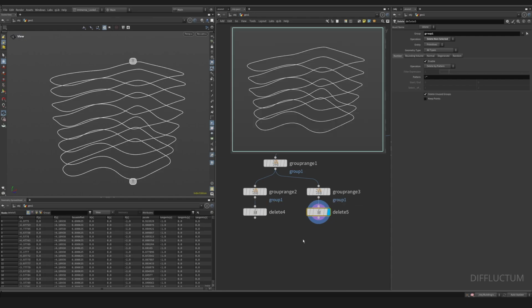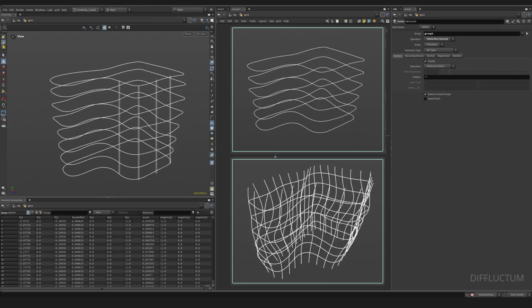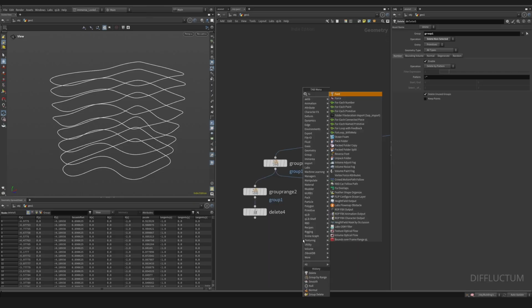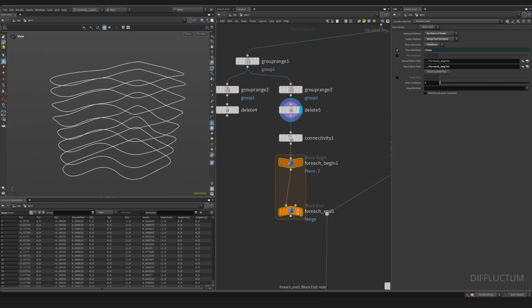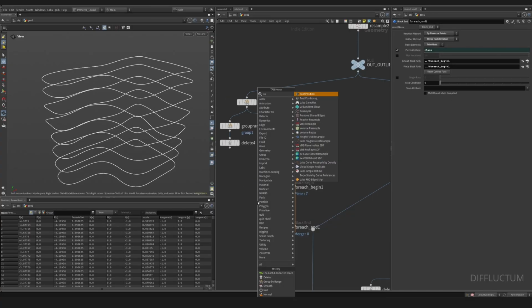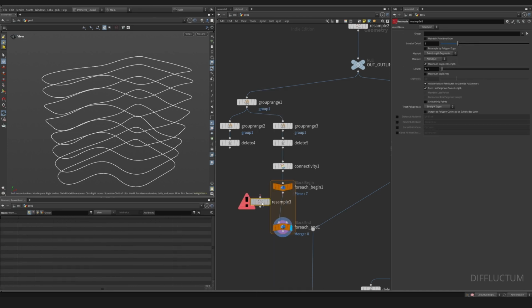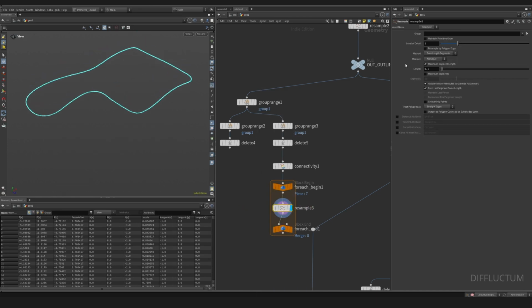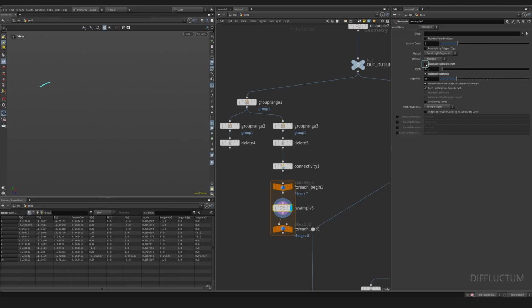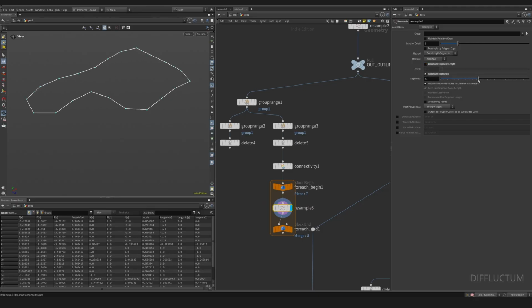So the curves without the top and bottom are our horizontal pattern lines, and with the other ones, we create the vertical tiling lines. Use a for each connected prim loop to iterate over each curve. Then inside the loop, move on by resampling the curves with a fixed number. Select here maximum segments and deselect maximum segment length. In my case, a value of 320 works well.